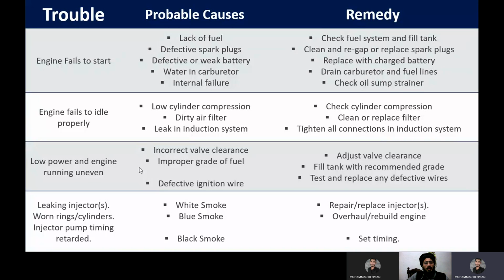The next problem is engine fails to idle properly, and other problems are written. On the third point, there is low power and engine running uneven. If the engine is giving low power, then first you can see why it is giving low power. It is due to incorrect valve clearance.